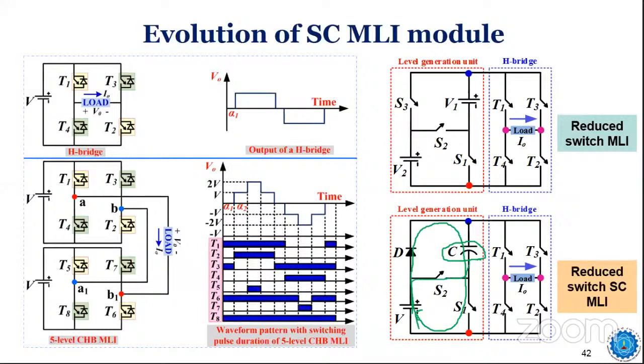So within one half cycle itself, we maintain charging and discharging. Again in the next half cycle, when the current is flowing continuously, this capacitor will be charged and discharged again. Because of the charging and discharging in parallel and series, we are always maintaining the required 50 volt across this capacitor without any voltage sensor or controller.